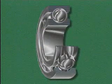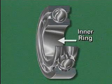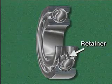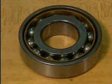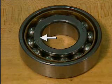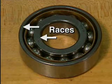While individual bearings may differ slightly, a typical rolling contact bearing consists of rolling elements, an inner ring, an outer ring, and a retainer. The rolling elements are either balls or rollers made of specially hardened steel. In this example, the rolling elements are balls, set between two hardened steel rings, an inner ring and an outer ring. These rings are often called races.